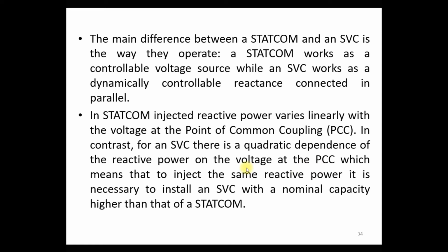As we already discussed in the last lecture, the reactive power Q injected by the STATCOM is directly proportional to the voltage, but in case of the SVC, the reactive power injected is directly proportional to the square of the bus voltage. PCC means point of common coupling, that is nothing but the bus voltage.